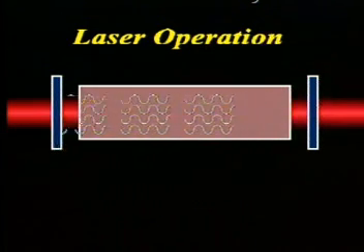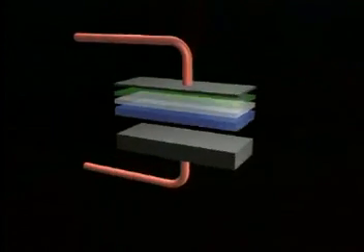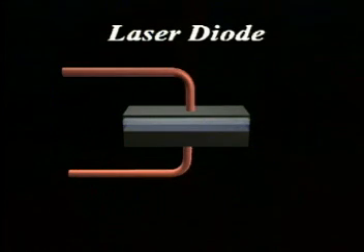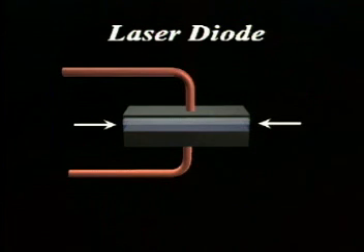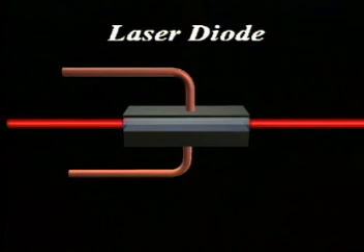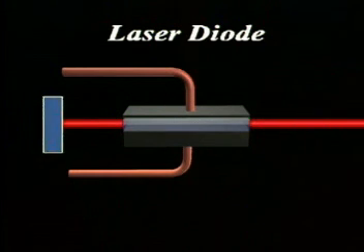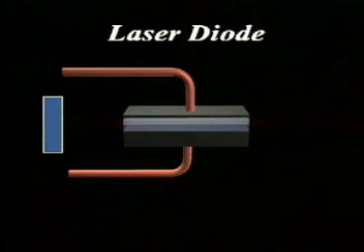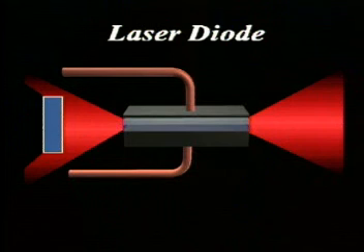The structure of a laser diode is similar to an edge-emitting LED. The resonant cavity is formed by cleaving the end faces of the semiconductor material to form parallel, highly reflective facets. In semiconductor lasers, a beam is available at both reflectors. A photodetector can be placed at one end of the laser chip to monitor beam power, allowing drive circuitry to keep the output level stabilized. In order for laser action to occur, the input energy to the device must exceed a certain threshold. Below the threshold, only spontaneous emission is produced, as in an LED.